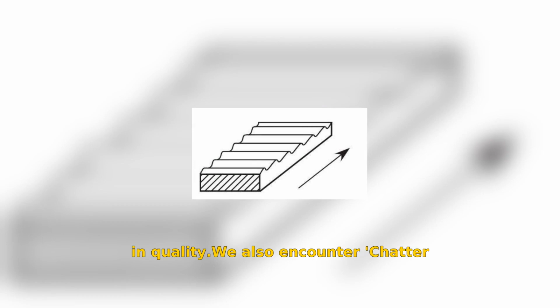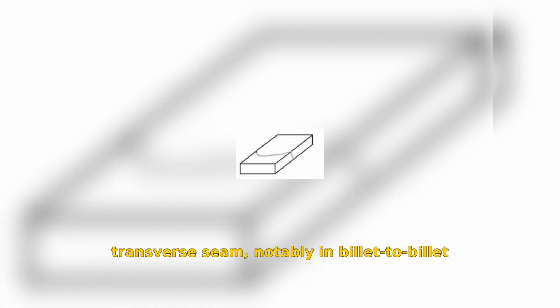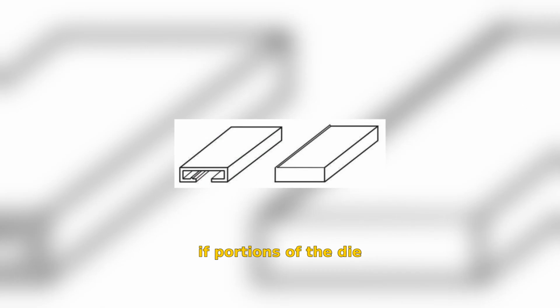We also encounter chatter marks, which are regularly spaced surface marks transverse to the extrusion direction, resulting from vibrations during fabrication. A stop mark appears as a circular ring indicating the area of the transverse seam, notably in billet-to-billet extrusion processes. Finally, we have snap marks, characterized by rings with cutouts across the extrusion, caused by abrupt changes in parameters during the extrusion process. Lastly, a broken die can distort the desired cross-section of the extrusion if portions of the die are missing or misaligned, leading to serious quality issues.